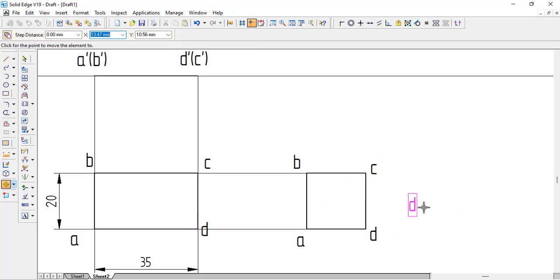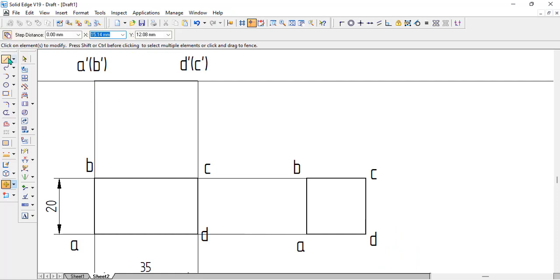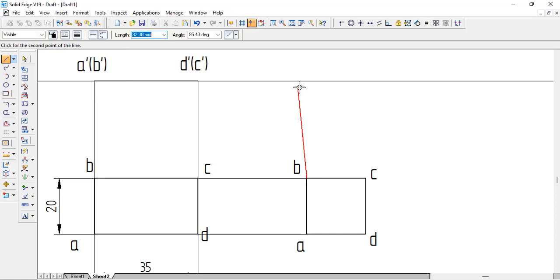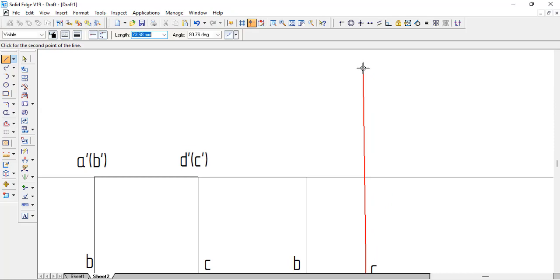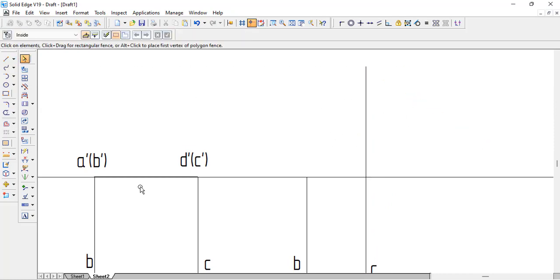Okay, so now when we come across the inclination, this line AB will be till the XY line because that is where it is rotated from, and one more line from CD will be somewhere, but CD will be lying on this line, though we don't know where exactly. But we know the length of this one. The same line is rotated, so we can go with the arc by center point.